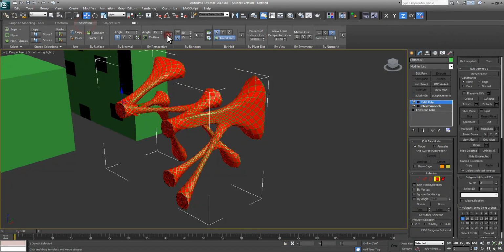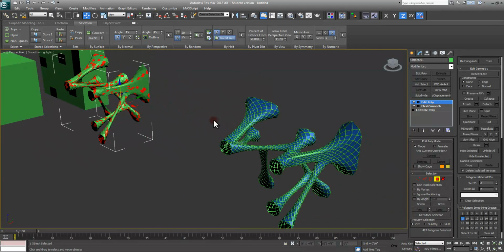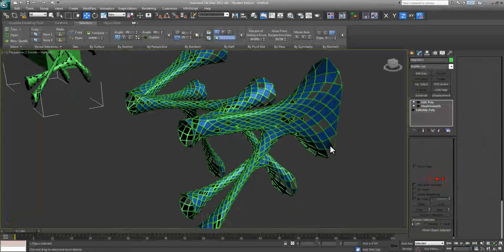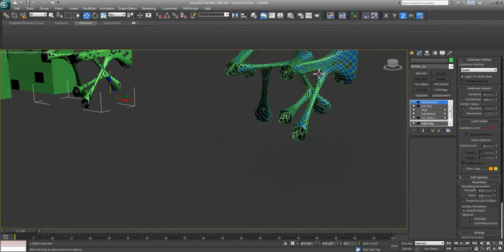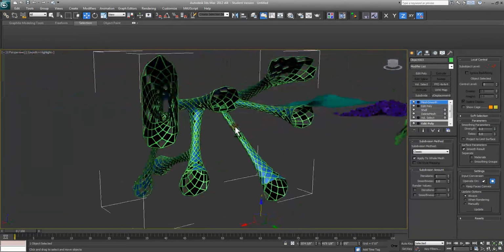I go selection 25%, selecting within the current selection, so it's only within ID number 2, selecting 25%, and as soon as I hit delete, I automatically see that update on my reference geometry. As I make modifications here, it'll automatically appear on the reference geometry that I'm working with. So it's a very handy tool to have and work with.